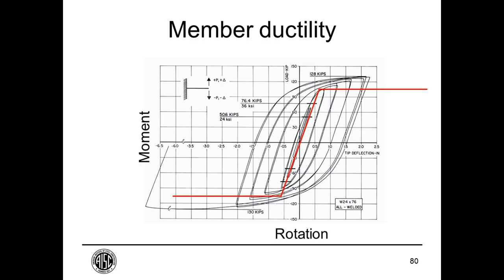Each of these systems has a force displacement or moment rotation graph that looks kind of like this. It's very reminiscent of the yield plateau. It's a bit more rounded because not all of the section is yielding at the same time. It has to go through a fair amount of rotation from initial yielding at the extreme fiber to developing of the pretty complete plastic hinge. Nevertheless, it does look like the steel stress strain curve, just a bit more rounded.